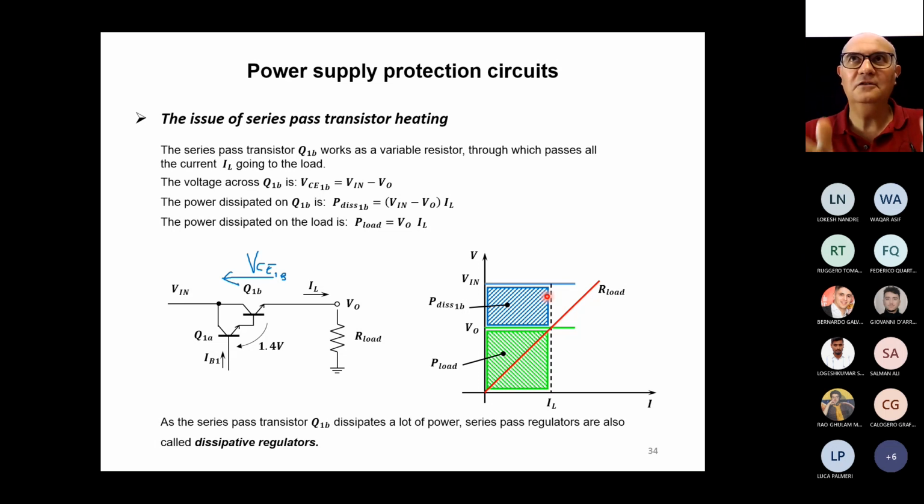And in this case, you start with a linear power supply, which generates almost no noise. You're not going to use a switching power supply that as soon as you switch it on will generate a mass of noise at any frequency. It's like committing suicide. Imagine that you have a radio telescope that wants to pick up the signals from far galaxies. You are not using a switching power supply for that system.